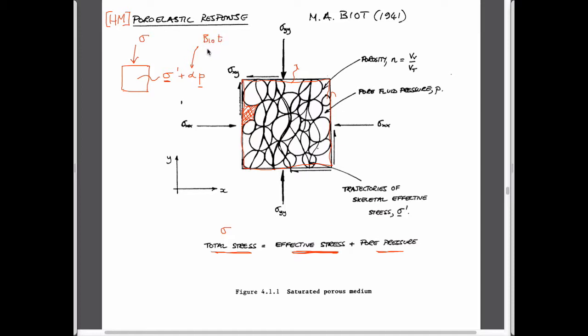And it's basically, we think it's equal to 1 minus the stiffness of the skeleton divided by the stiffness of the grains. And so when the stiffness of the skeleton is tiny, in other words, these grains can deform next to each other, then this ends up being 1. And if the stiffness of the skeleton approaches the stiffness of the grains, then it is equal to 0. And there's no actual effective fluid pressure modulating behavior.